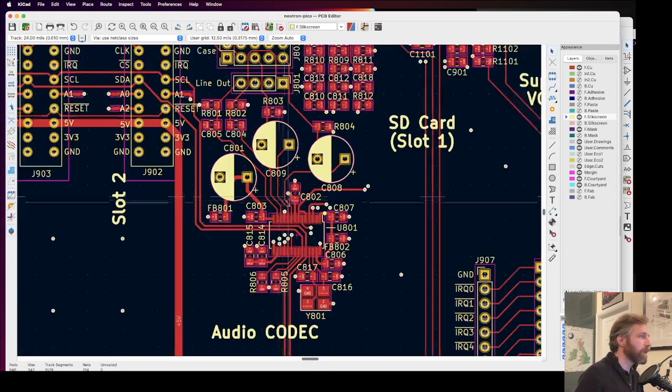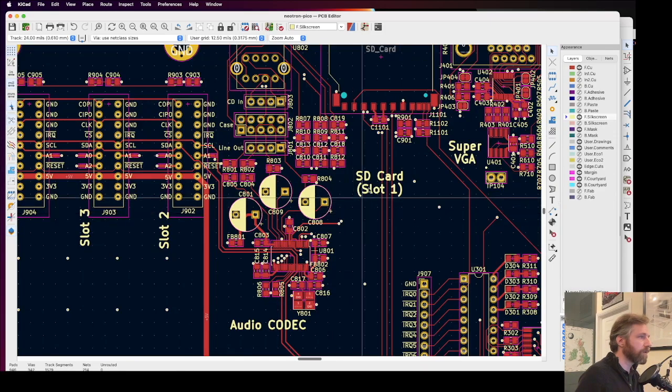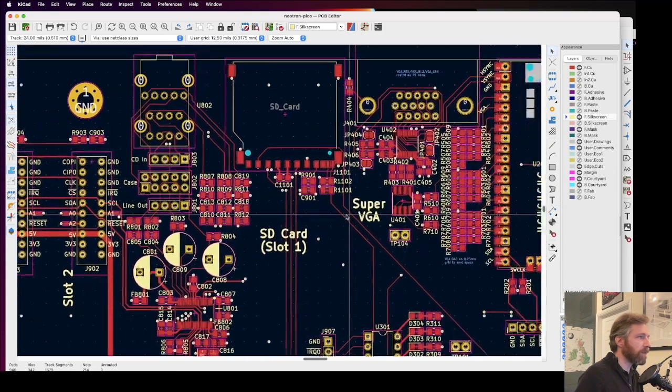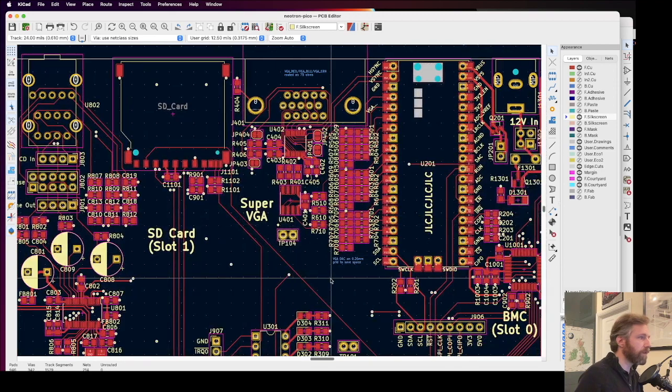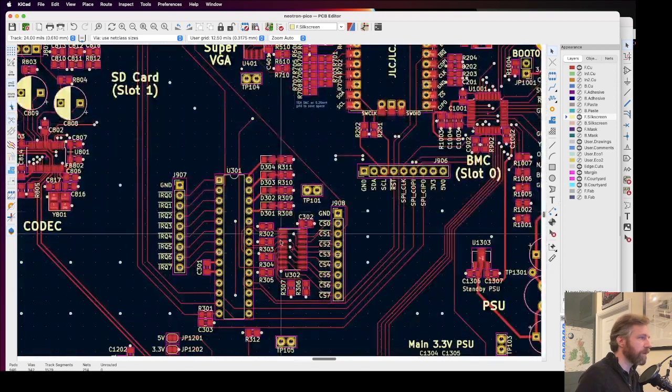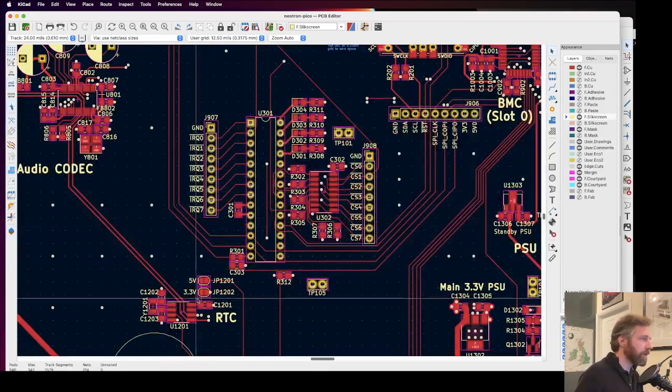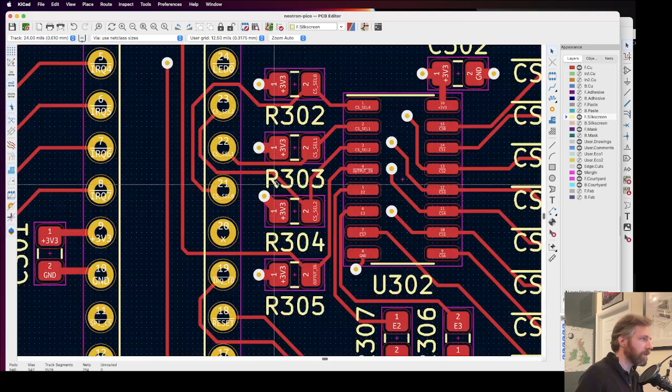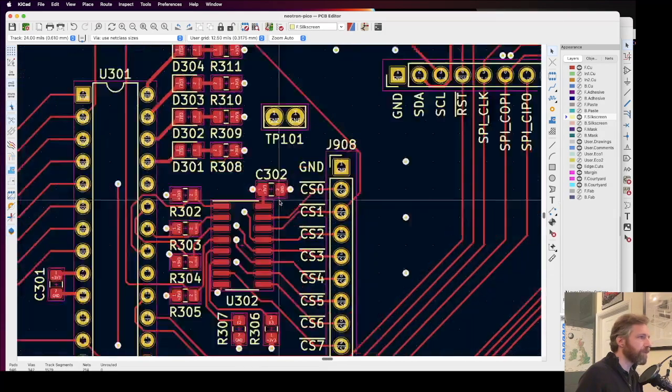Do I have any more vias fouling my silk screen? Scrolling around, and we haven't looked at the I/O circuit yet. We did down here. These seem fine, these seem fine, these seem okay. 2, 3, 4, we are. Check my silk screen is all in line. Yep, that's all lined up, looks fine.